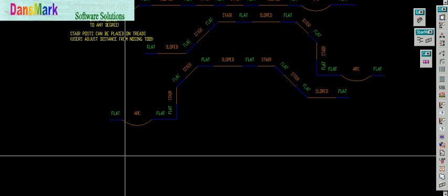Well, this is going to be continuous, so we're going to type in C. If it was towards you or from you, you would type in either T or an F. We're going to type in C for continuous. It will be an arced, and we'll put in a 12-inch rise for the arced railing, and it's done.